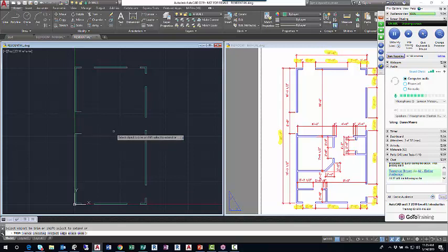Now the green grid line is almost the exact same color as the wall lines that I chose to use. You can kind of see the green grid line extends beyond the top left side of the plan. It's present in the door opening, and then it's obscured by the wall line below the door opening. So don't let yourself be fooled to think you have to trim 100 times to get that line to go away. That green line is the grid, the drawing grid. I'll click off the horizontal lines, and there's the result there. I'll save that.